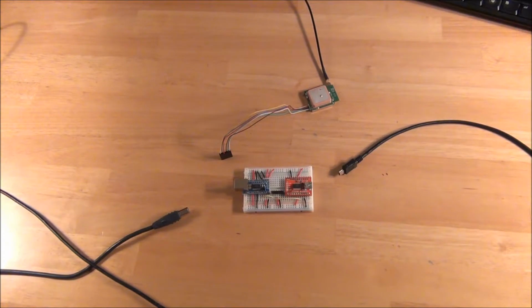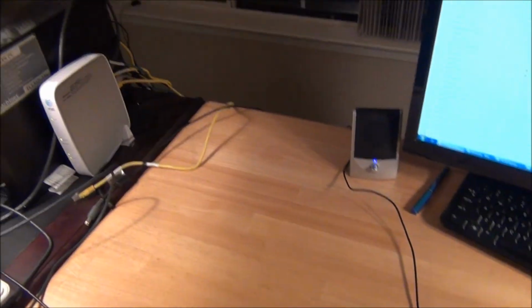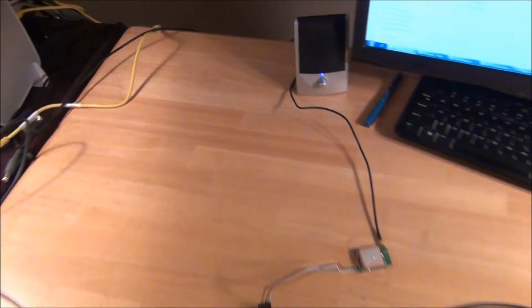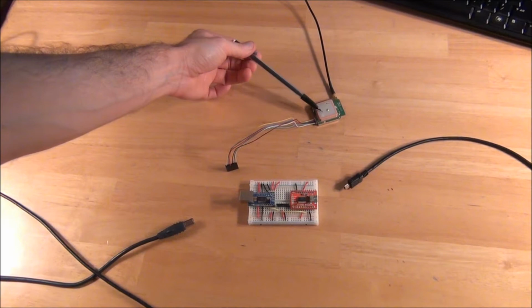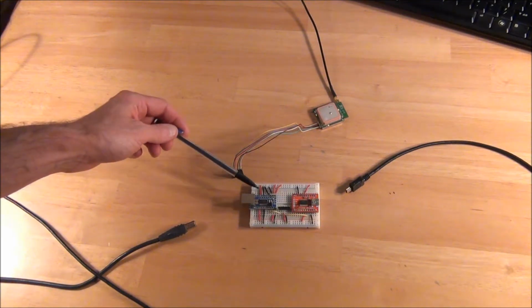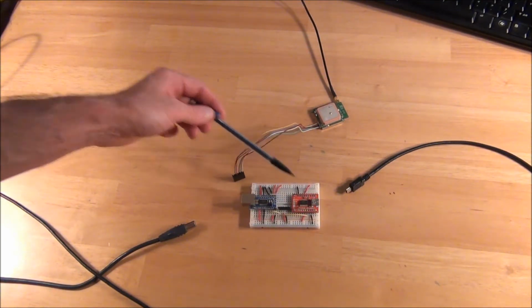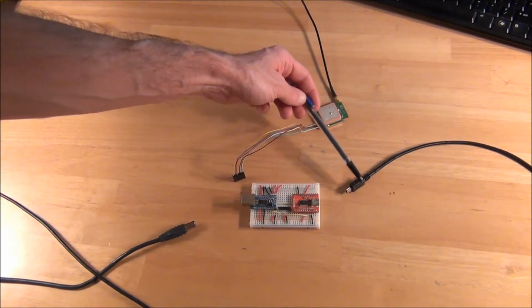So here's our breadboarded circuit. And at the top here we have the PMB688, and where that wire is going to is on my windowsill over here in the background a little bit. Sorry for the squeaks on my cheap tripod. That's the GPS antenna. That's about as close as I could get it to being outside without actually being outside. And now if we pan back to our circuit, so we have our PMB688, and then this is the cord going to the antenna. Here's the PMB688 connector. Then we have the Arduino FT232 breakout board, the SparkFun FT232 breakout board, our USB standard size B connector, our USB mini B connector.